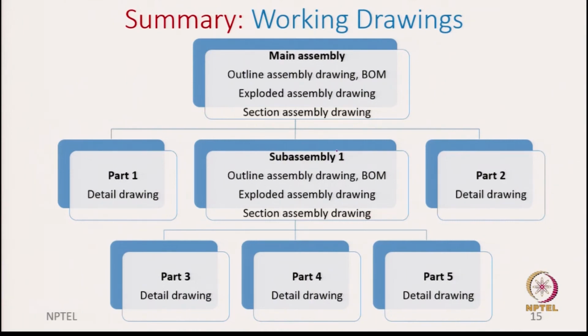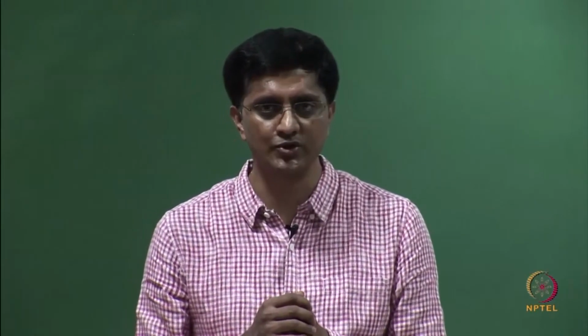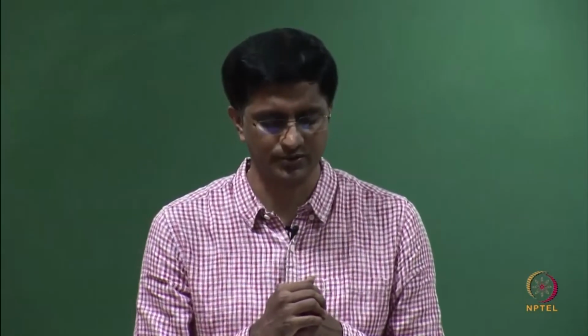And when we discussed these section assemblies, in our examples we have only shown them for multi-view projections, but section assemblies can also be done at the pictorial level depending on the purpose or who you are showing these drawings to. If you are showing these drawings to a non-technical person who is not so exposed to these projections, then usually we show the pictorial projections because those are easy to understand. But if you want to convey more precise information, that is when we go to the multi-views.